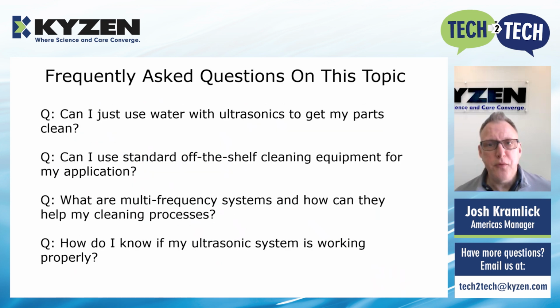So let's talk about a couple frequently asked questions on this topic. Often we're asked, can I use just water with ultrasonics to get my parts clean? The answer is absolutely yes in some cases. If you're really looking purely at particle separation, it's possible that DI water and ultrasound may be enough to do the cleaning work for you. However, it should be noted that even here, in a lot of cases, it's desirable to have some level of surfactant in the solution, again, to help promote cavitation.